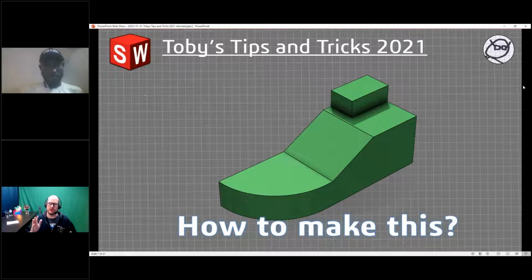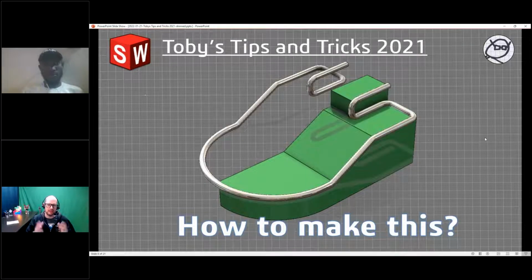We would just do maybe a boss extrusion of a tombstone shape, an arc, a line, an arc. We would maybe do a cut extrusion to create this little downward sloping area, and then we would create this little rectangular area up top. Well, what's cool about SolidWorks is that if you create this geometry, you can then use that geometry to generate that complicated wire, that complicated sweep.